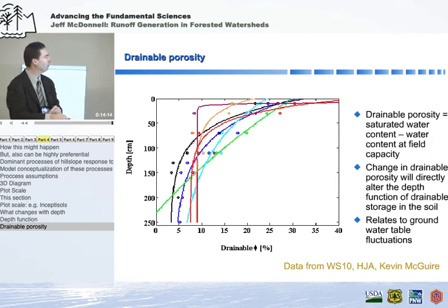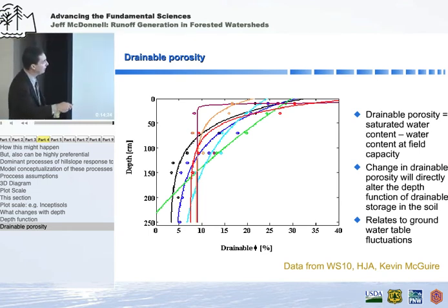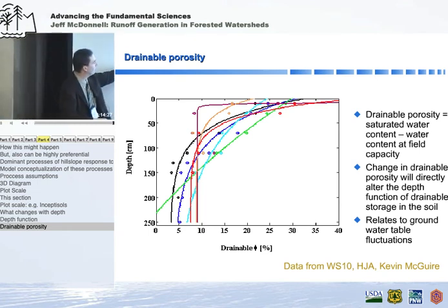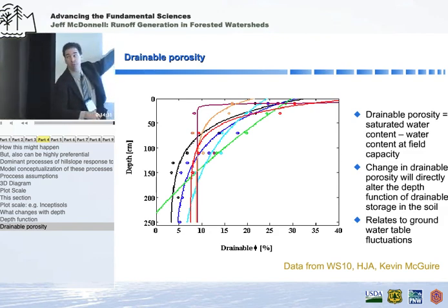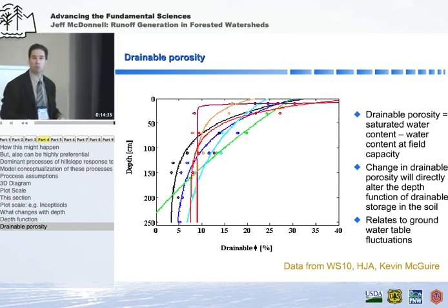This is very important for slope stability, but for runoff generation, this is often the hot spot where runoff is generated. Now, this notion that hydraulic conductivity declines with depth is important as well, because then as water tables begin to rise into the more conductive soils, that's when we can also enhance lateral flow towards the stream channel.